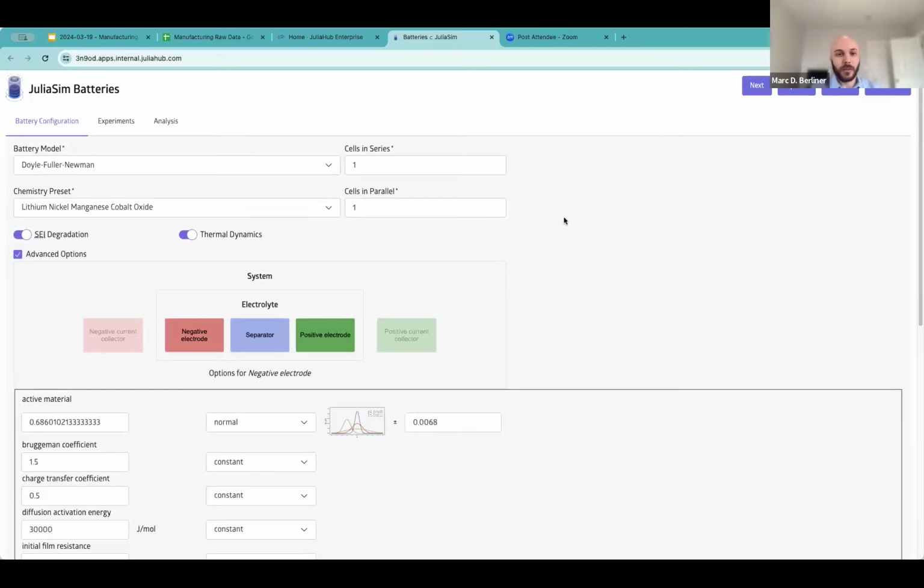Yeah, so like Ranjan mentioned, we're working with an SEI capacity fade model. Physically, how this works is there's a parasitic side reaction on the anode, and this consumes some of the overall intercalation. Eventually this builds a layer which grows on the anode and leads to a reduction in the state of health. So this is an empirical model, but we found it to be pretty good for some sources from the literature.